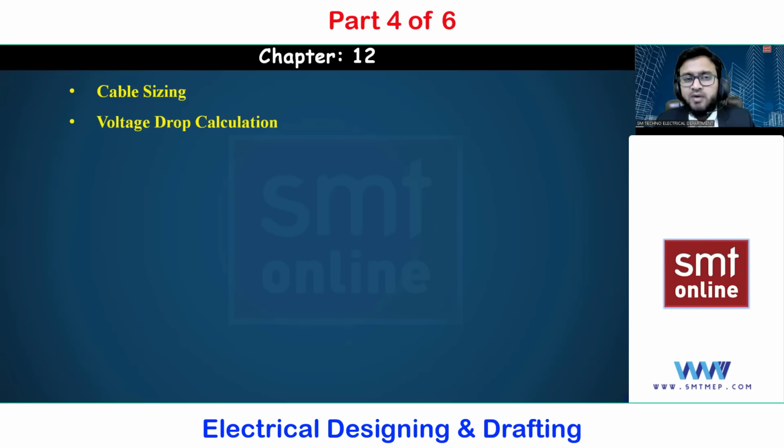Once you have defined the cable sizing, after completion of that, we shall go with the second step of calculation in the same cable sizing, which is called voltage drop. Okay, why is it necessary to go with voltage drop? Remember that whatever amount of voltage you are sending, it is not compulsory that the same amount of voltage you will receive. There can be a drop because of internal losses or any kind of exterior losses also. So in this voltage drop, we are going to find out the percentage value for the high tension side as well as for the low tension side.